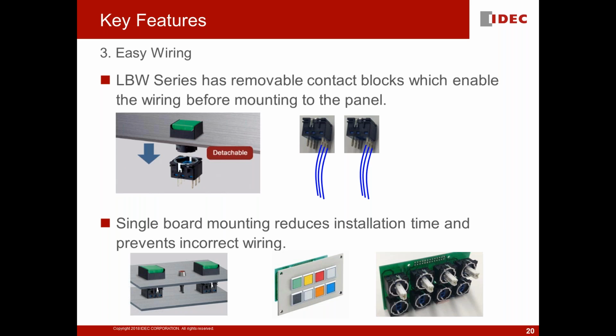Another example of reducing wiring labor is what you see on screen, in the bottom right corner. This is a group mount technique. We have all the contact blocks prefabricated on a PCB, and you can see there are 2 rows of pins, which is designed for a connector. So you can basically connectorize a group of switches and do group mounting all together to save labor,